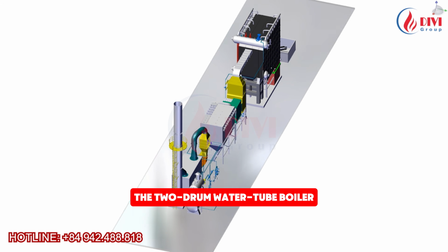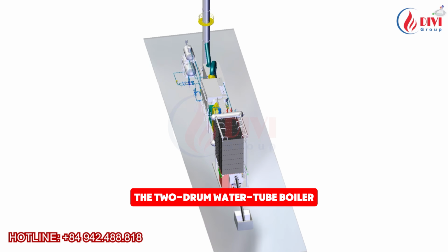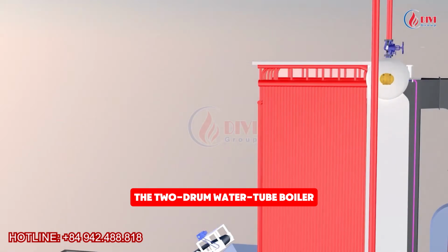Next is the two-drum water tube boiler. In this design, the furnace walls are formed entirely by water tubes, which absorb radiant heat and generate steam. The convective heat transfer section is also made entirely of water tubes. These water tubes connect the upper and lower drums. The lower drum mainly contains water. The upper drum contains both water and steam.